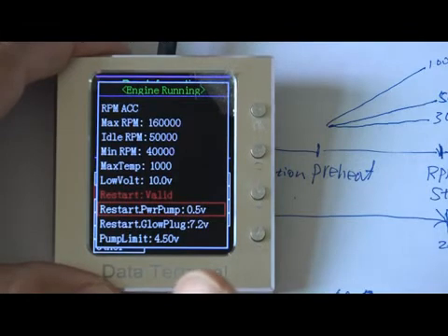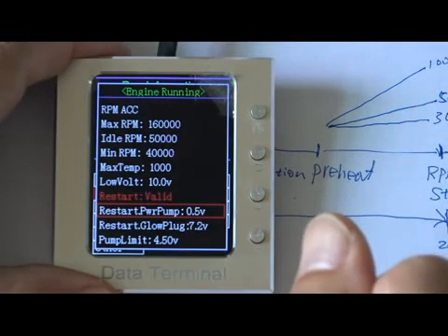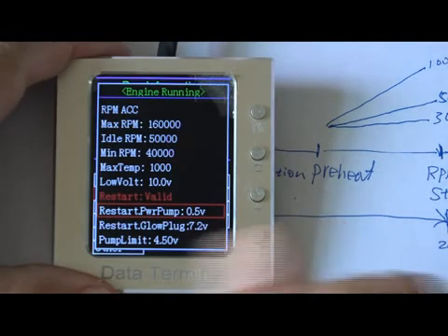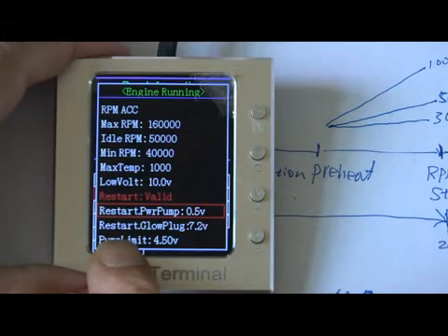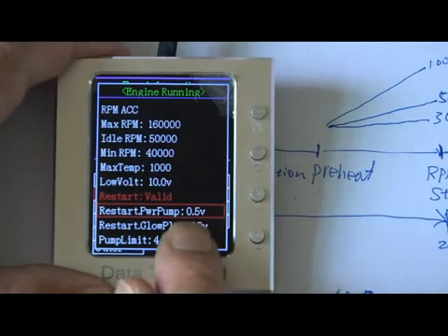You need to test your turbine on the ground. When you pinch the fuel tube, the turbine will go into auto restart. And if you find too big a fire when auto restart, you can reduce this voltage.